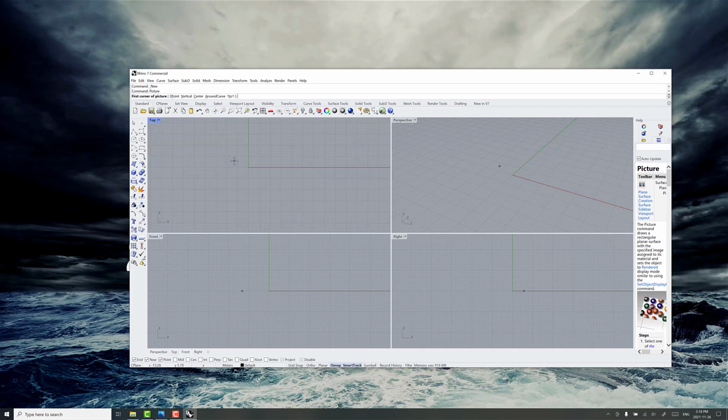Now you want to make sure that it's inserted to scale in meters, and oftentimes you'll have the UTM coordinates of the corner location or some location in the image. So we're going to do the top left of the image. This has been offset. It's a real site, but it's offset.